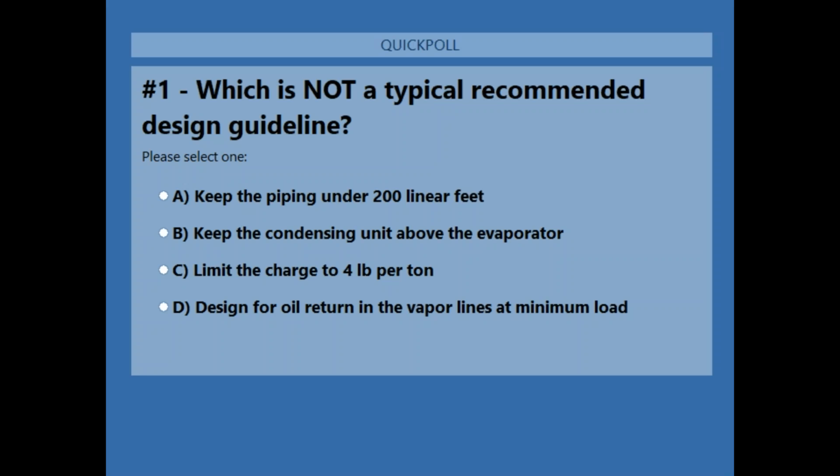Okay. So once we get that, we have the equipment. My salesman will give us the submittals on the evaporator coil and the condensing unit, or the chiller and the remote barrel. And from there, then we can kick back to you the pipe sizes, if you need double suction risers, if you need double discharge risers, and what their A and B pipe sizes are. So we provide that to you.